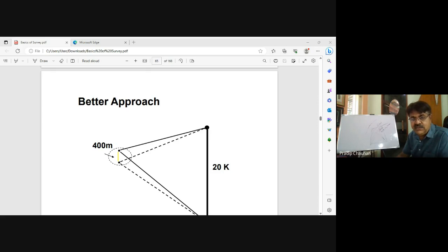If it is rail, then one track will be at a higher elevation compared to the adjoining railway track. The reason is to accommodate the speed of the railway. And if you are not designing it properly, your vehicle may overturn towards the center or away from the center. Okay. So here the survey is important.